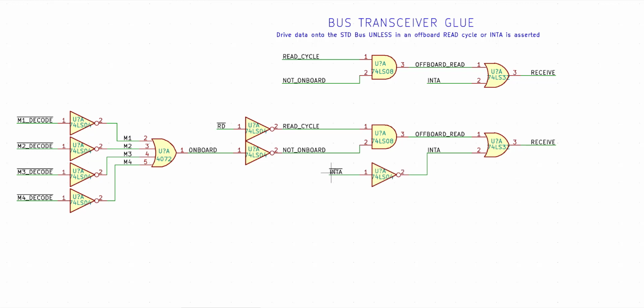The logic of the receive output matches the receive not send on the board, so I just need to add a name to that signal. This gives me the first usable circuit since all of the signal names are actual board signal names. I had to change this bottom one. This is actually the 8155 chip enable.